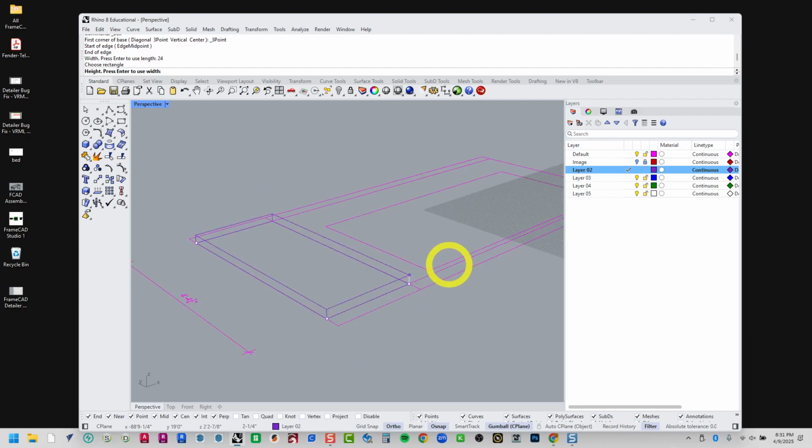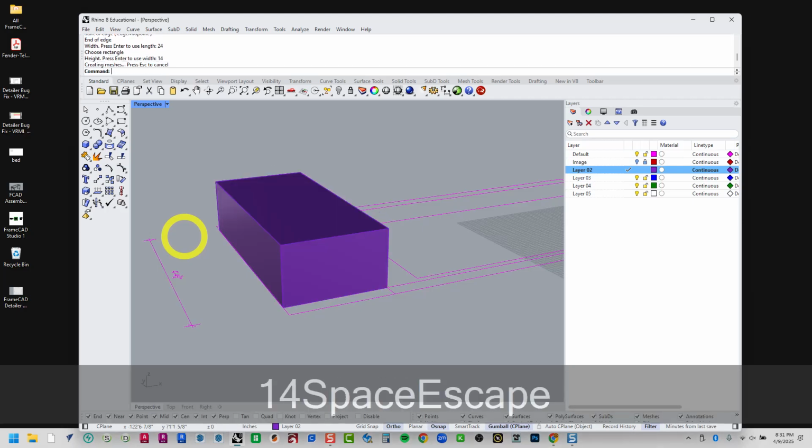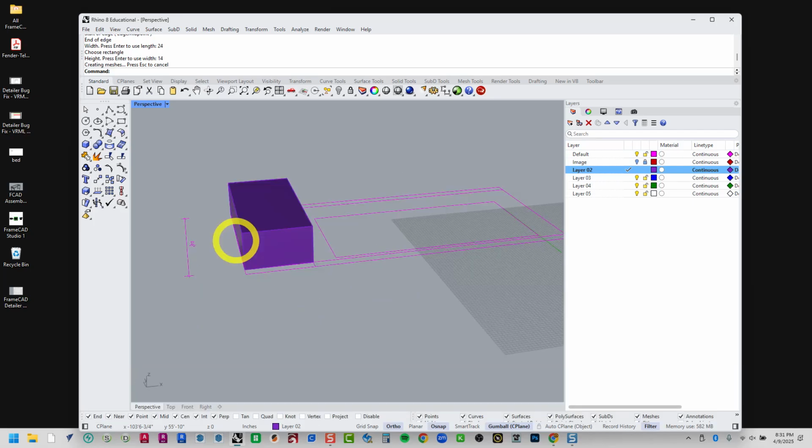Let's also model the frame as if we're going to put some subflooring down, just a big sheet of plywood or maybe a couple of pieces of plywood. So let's go to, let's call this layer 2. Let's give it a name, call it cabinetry. Let's go to layer number 3, put that check mark on layer number 3. This will be subfloor, so I'm going to find some wood looking color.